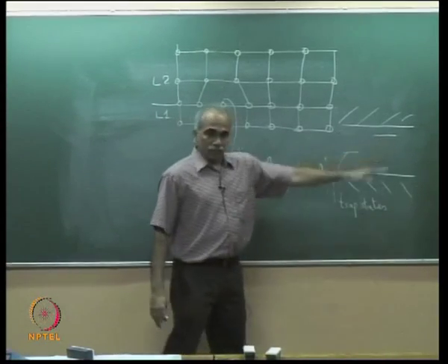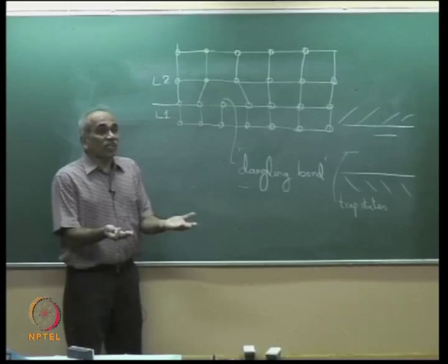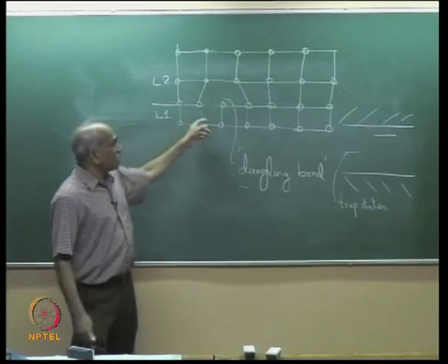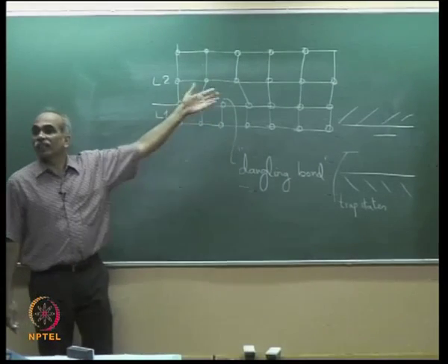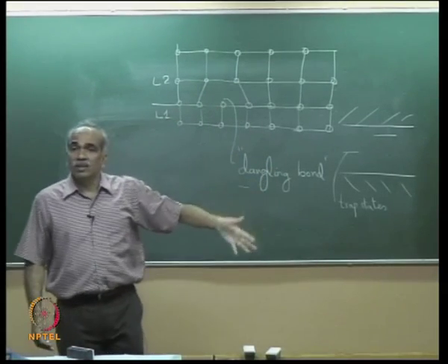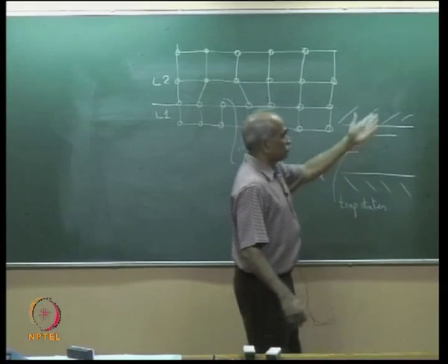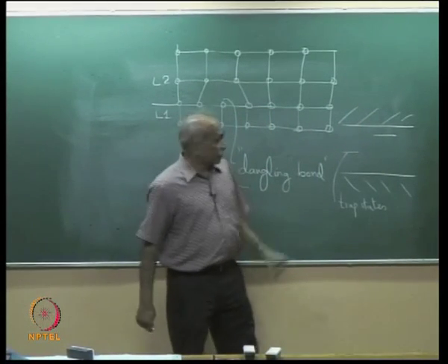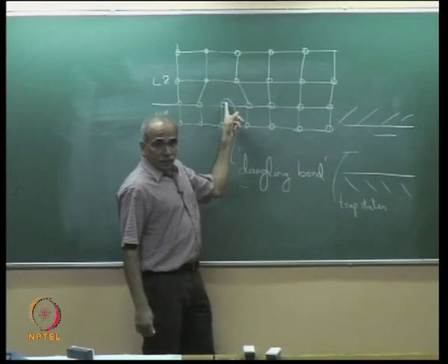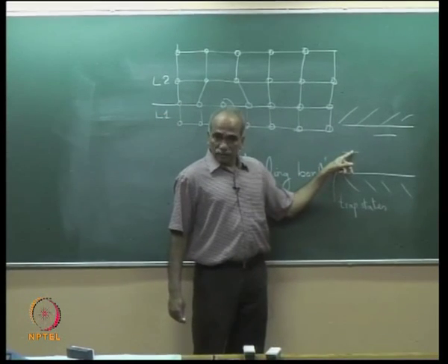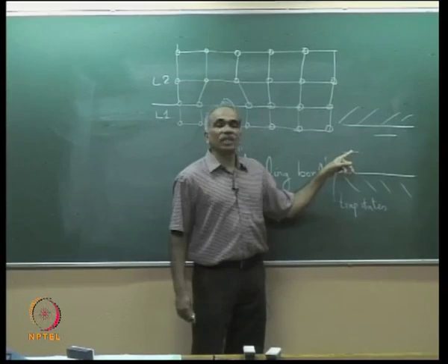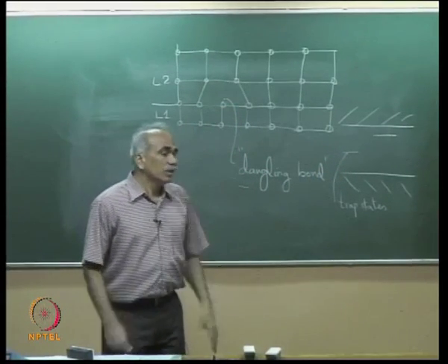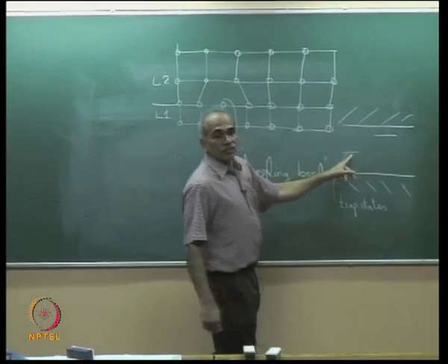But even if the two materials are very pure, with no impurity, if the lattice does not match, then the dangling bonds will have energy which is different from the rest of the electrons which are forming the bonds. And if the energy corresponding to these happens to be in this gap, then they are like trap states. Trap states increase non-radiative recombinations.